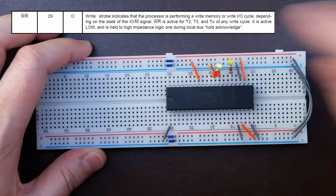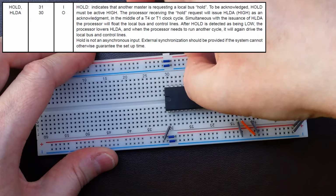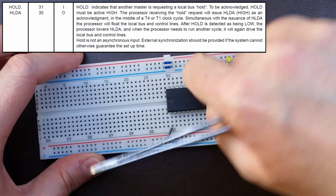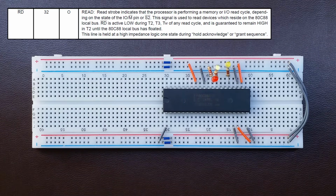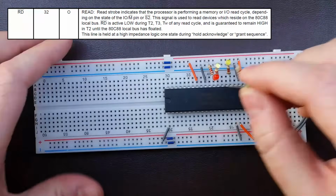Pins 30 and 31, HLDA and HOLD, are a pair of pins used to take ownership of the address lines from the CPU by another device on the bus. We're not going to use them, so we just need to pull the HOLD, which is an input, to its inactive state, low. Pin 32, RD, is similar to pin 29, WR. It is active low whenever the CPU wants to read data from the bus. Let's stick a green LED between this pin and the VCC again.